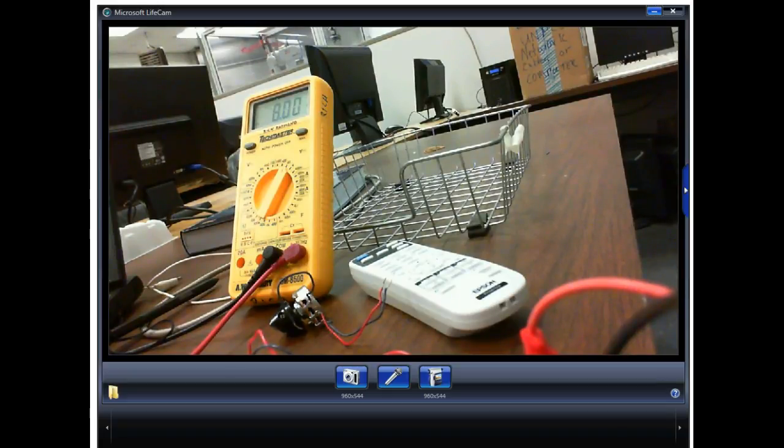We expected it to go way up, right? We could have pretty close to calculated it. So if the base voltage goes up, the emitter voltage goes up, means the voltage drop across that. So here's my emitter voltage right now. We should expect it to be 0.7 of a volt lower than the base, so it's 0.7 of a volt.